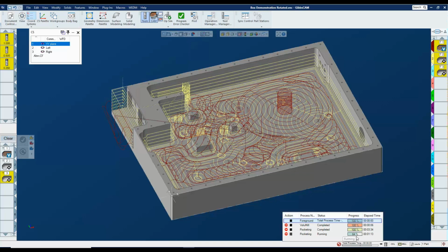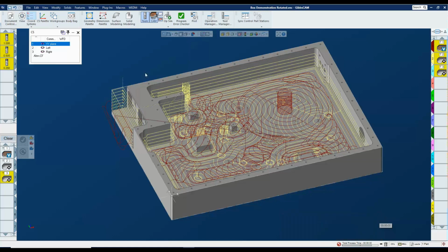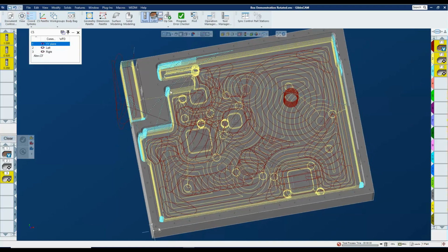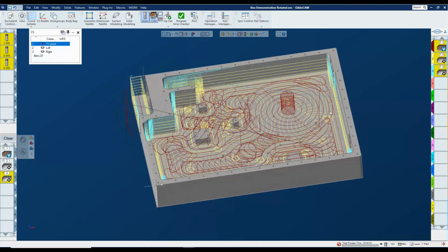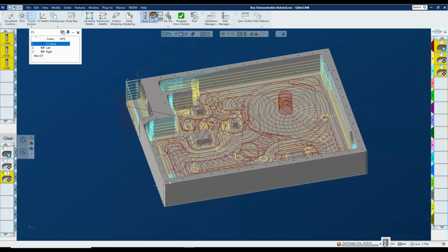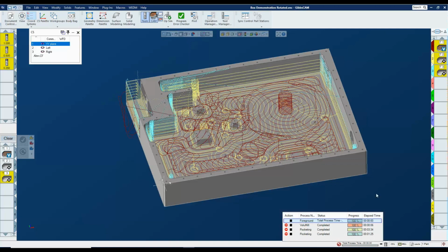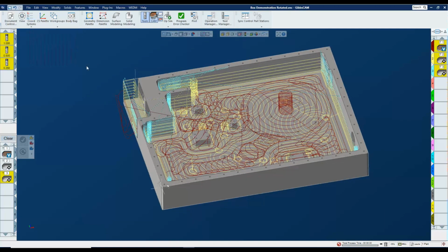We're just about there. This one's at 64% right now, so it should be done momentarily. But I've gone and set up my coordinate systems the way I want to. You also notice that we have color coding on, so I can actually see each toolpath in its own color. Okay, so the red is your volume mill, the yellow is the secondary op, and the blue is the tertiary, third op. And so you can see how each one is only cleaning up what the other one left behind. And I think at this point you notice it now says 100%, so we're all done with that.